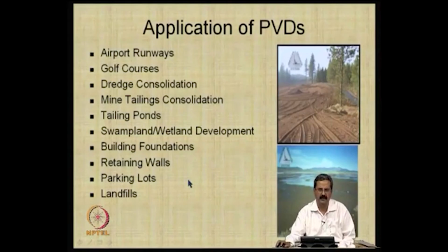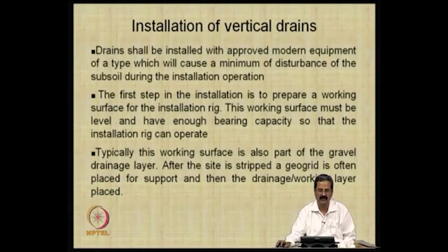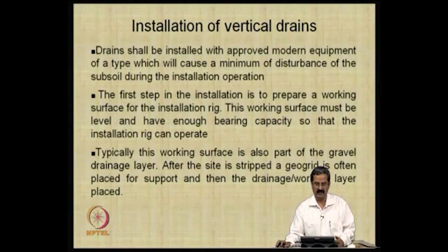Wherever there is a possibility of accelerating drainage or the consolidation response, these have been quite effective. Nowadays, installation is done with modern approved equipment such that there is minimum disturbance to the soil, so that it does not lead to the permeability being low here.